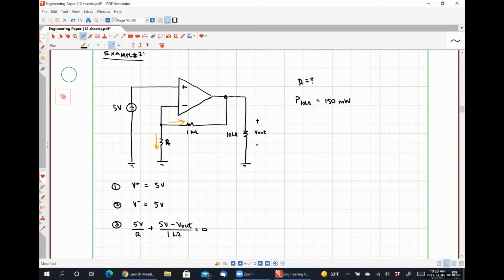If we knew the value of R, then no, it shouldn't. Exactly. So it doesn't matter what our load resistor is that's connected to our output. Our output voltage is effectively independent of what we have this connected to, other than a short circuit, which would force it to be 0.